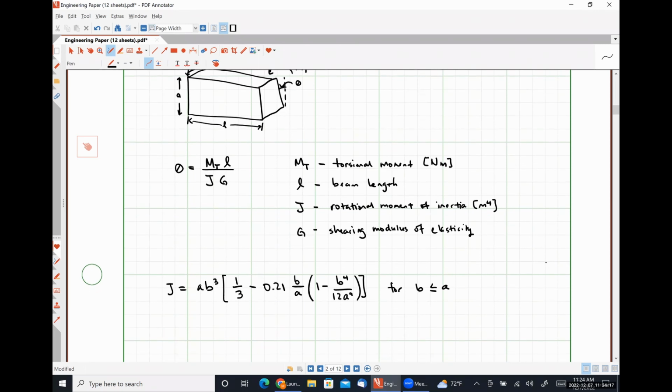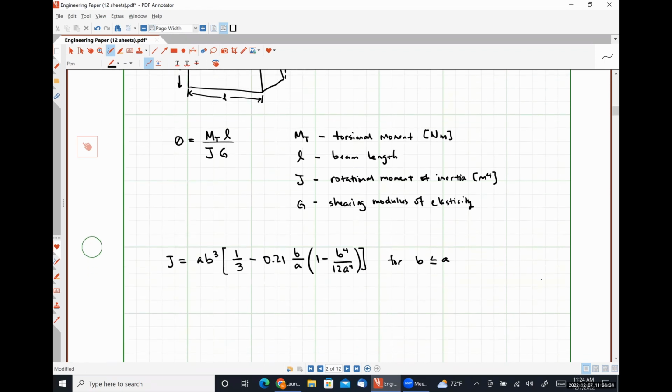So what we're going to do here, this is literally an equation just from a textbook. Actually, it's a combination of equations from two textbooks that I made work to suit my needs, but that's neither here nor there. Because this is a spring, we're going to effectively force Hooke's law to work for this. So what I mean by that is Hooke's law for torsion, MT, will be given as K theta. So this is going to be our rotational spring constant multiplied by theta, which is our angular displacement.